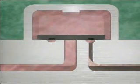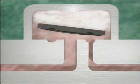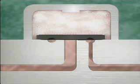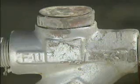Condensate that comes to the trap in the middle of a time cycle won't be discharged until the pressure above the disc falls low enough to allow the disc to rise and reopen the trap. Since the movement of the disc cycles between the open and the shut positions, the discharge from the trap is intermittent. Many of the maintenance problems associated with thermodynamic steam traps are due to wear of the trap components.